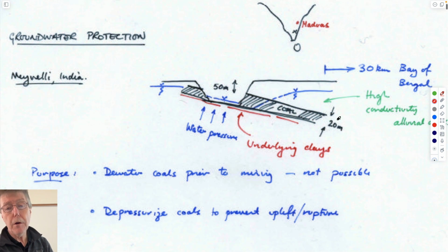And so the problem here is, one, the water pressures are so high that when you take away the impermeable coal, all of a sudden you're swimming in the pit because there's so much water goes into the pit. And secondly, you can pump that out, and it turns out that all the area around Nivelle is very verdant and lush because they use it for irrigation, and further away it's much more arid. And secondly, the other problem is if you're pumping water here, then you get the same problem as in Florida, and that's groundwater intrusion.